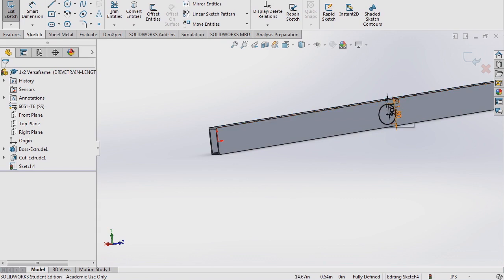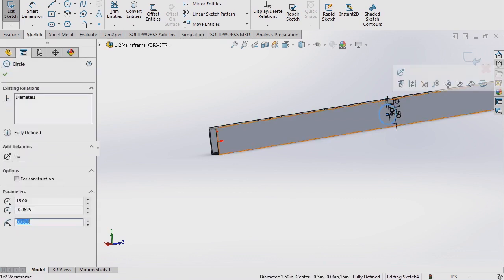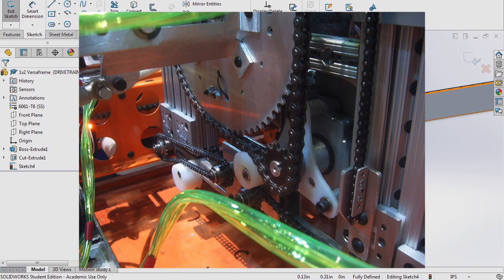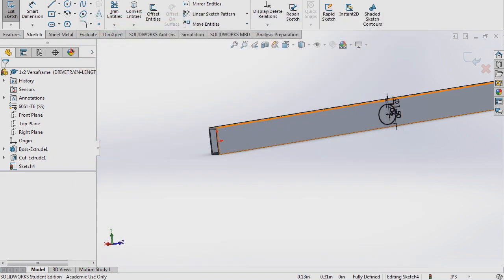So this center wheel where the gearboxes are, that's going to be fixed because our bearing block is fixed. And with our outer wheels, we're going to mount them to bearing blocks that we can slide around so that we can move the outer sprockets further apart from the center, and make the chain tensioned and tight again. In mechanisms, you're not going to see this as often. You're going to see more of this method, just because it's more space efficient compared to the drivetrain.